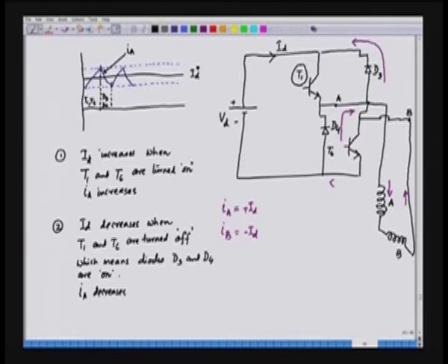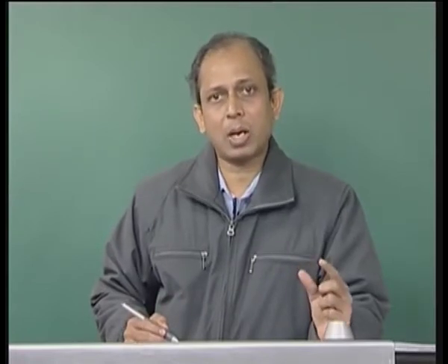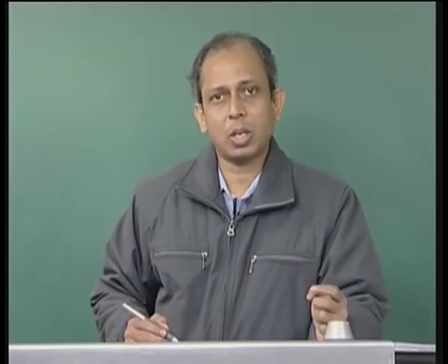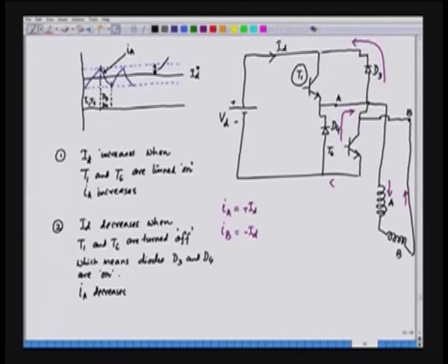The current can go high or increase, and current can also decrease, and this is done within two bands, and this band is called a hysteresis band. So, in fact, we have one band called upper hysteresis band and the other band called the lower hysteresis band. So, this is the upper band, and this is the lower band. So, if we control this current within two bands, we can keep the current approximately quasi-rectangular in nature.